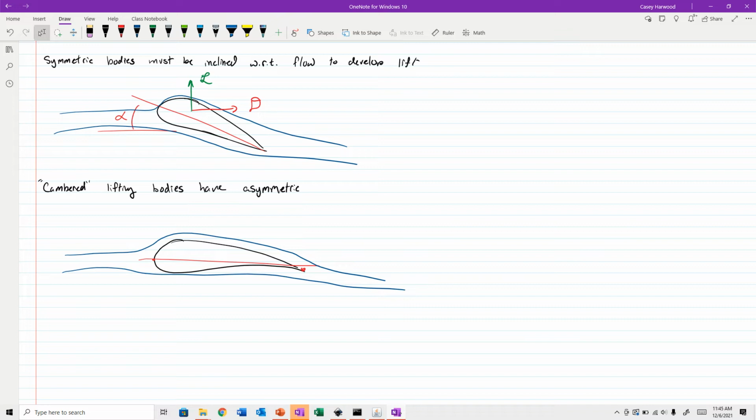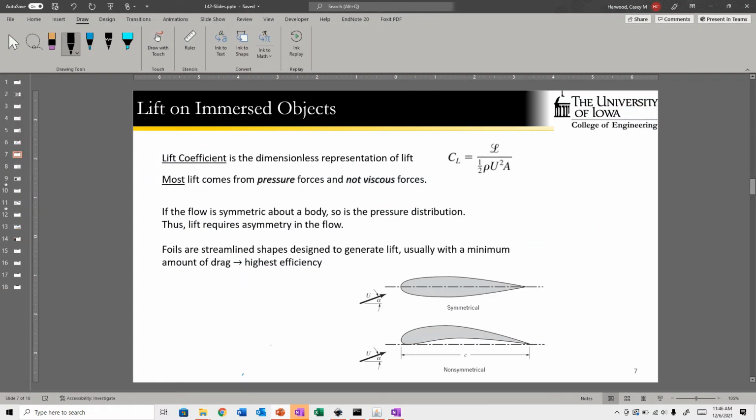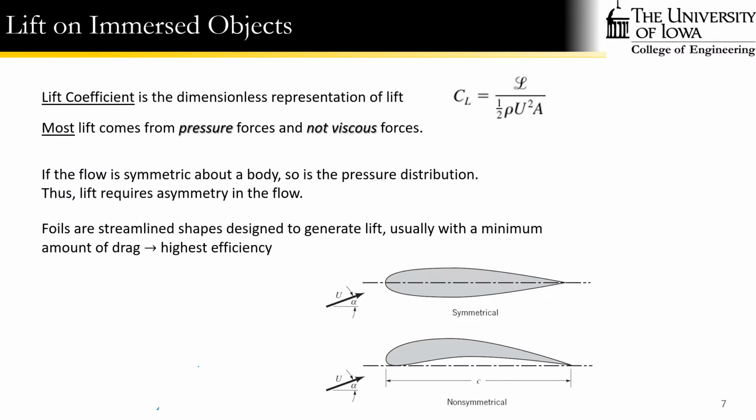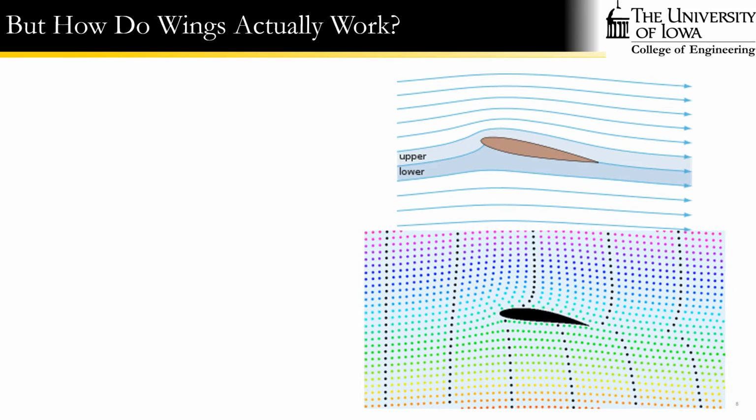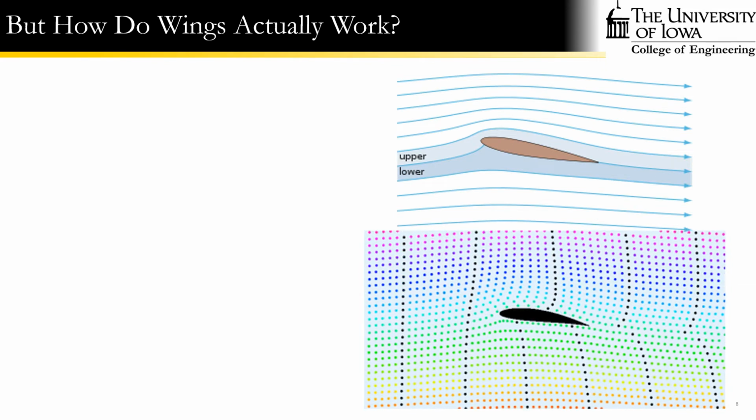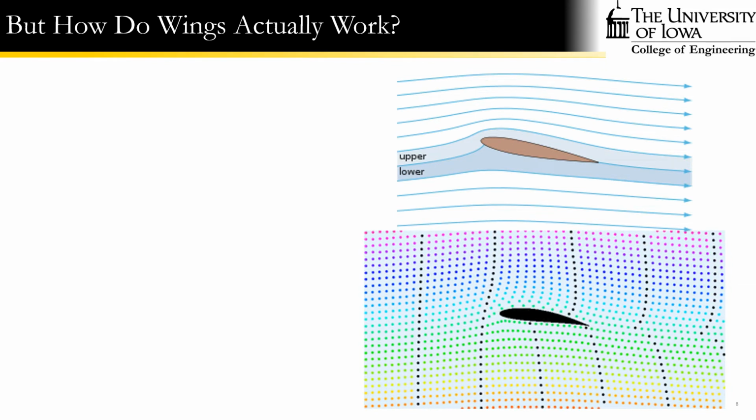Okay, that's completely wrong. That's called the equal transit theorem, and it has been debunked time and time again, but they still teach it in flight schools and engineering classes, but it's not actually correct. So the idea there relies on the idea that two fluid particles have to meet up with one another after they are done traversing the wing, which isn't really true.